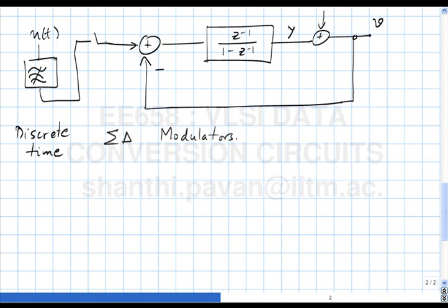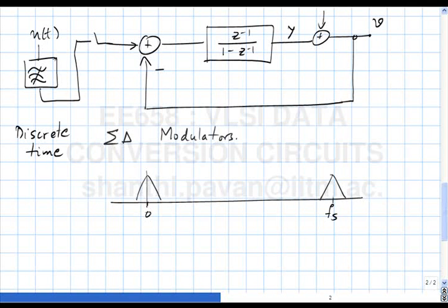correct? Because if this is the input signal, and you're sampling at fs, the band that will all alias back into the input when sampled is basically this band around multiples of fs, correct? So the anti-alias filter is something that needs to reject the alias to a sufficiently large degree to prevent noise from that band getting aliased into the signal.